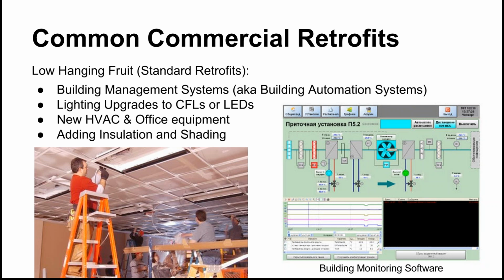So if they were having a problem with one of their air handlers, we could really quickly jump on and say, okay, I can see that it's this particular air handler, and this seems to be what's going wrong, and the temperature is too low as a result of that. So it's a nice, easy way to quickly see problems and to quickly regulate things. And if something happens and things get left running when the building's unoccupied, you can remotely change it. In addition, it also does a really good job of tracking your energy use and can make some nice graphs, some of those things that Karen talked about that help you monitor and compare your buildings to other buildings.